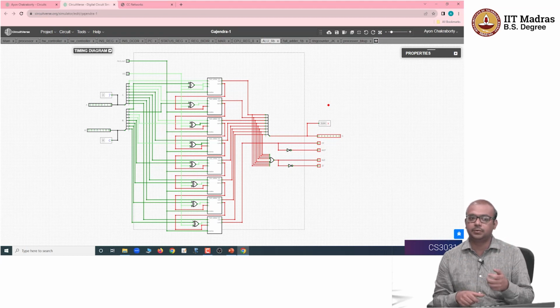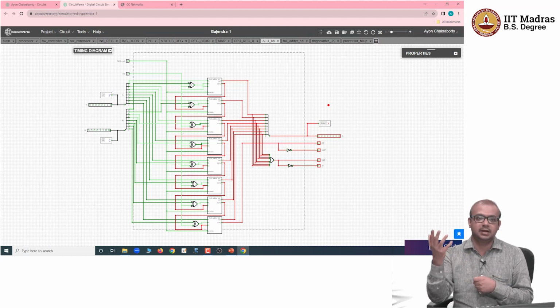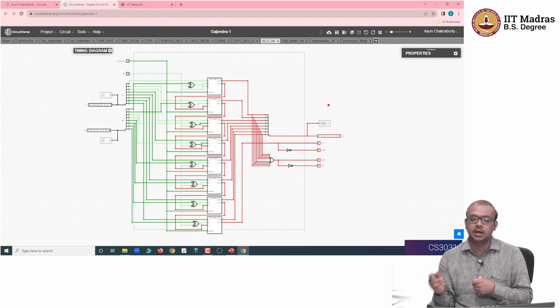The last 4 bits are going to indicate either an address, if you are trying to refer to an address and load that data into the registers, or an immediate value, which is again unfortunately 4 bits, because I do not have any more bits to accommodate in our instruction format. It's 8 bits, right? So the immediate value can only go up to 15, right? 0 to 15. Okay, so that is all.